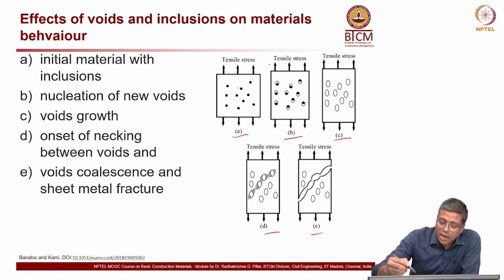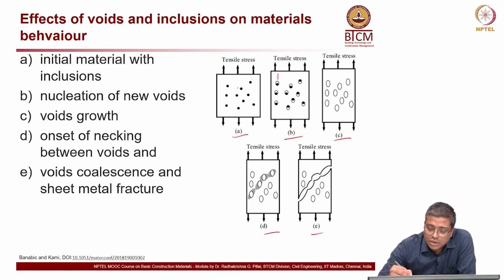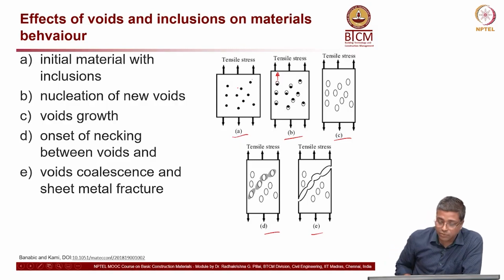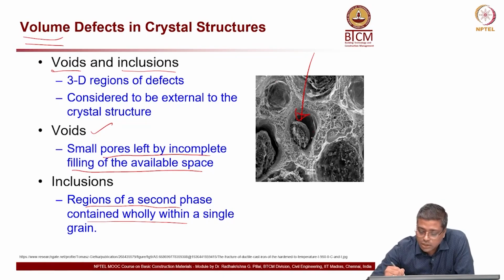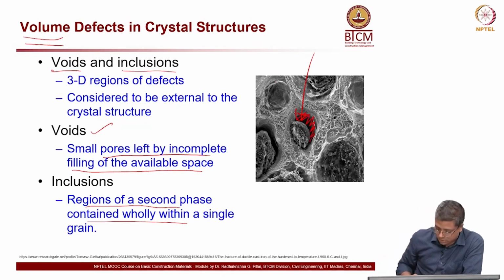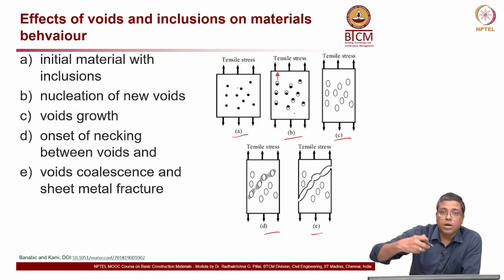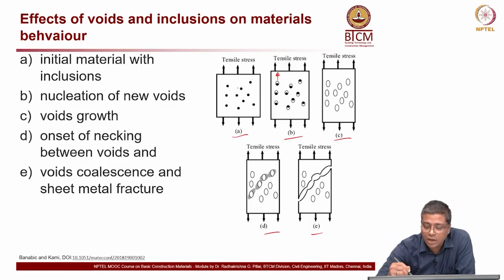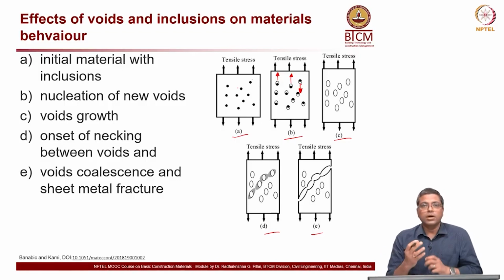As you apply this stress, what will happen is, here you can see this particular portion getting elongated this way, and then void inclusion is there. If you go back into the previous thing, you can see this space here. So as I pull, that inclusion gets detached, and then you have a stretching happening here. Here you can see the other way. Here you can see it is getting pulled this way, right. So like that this deformation happens.